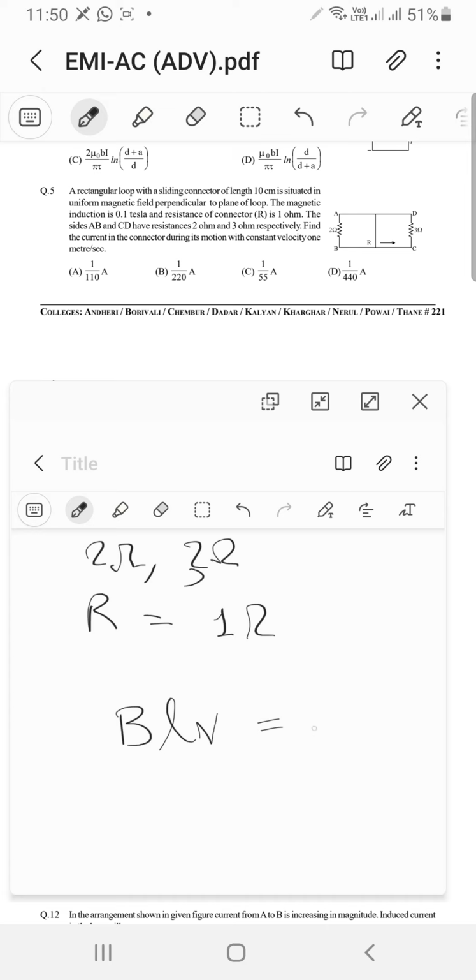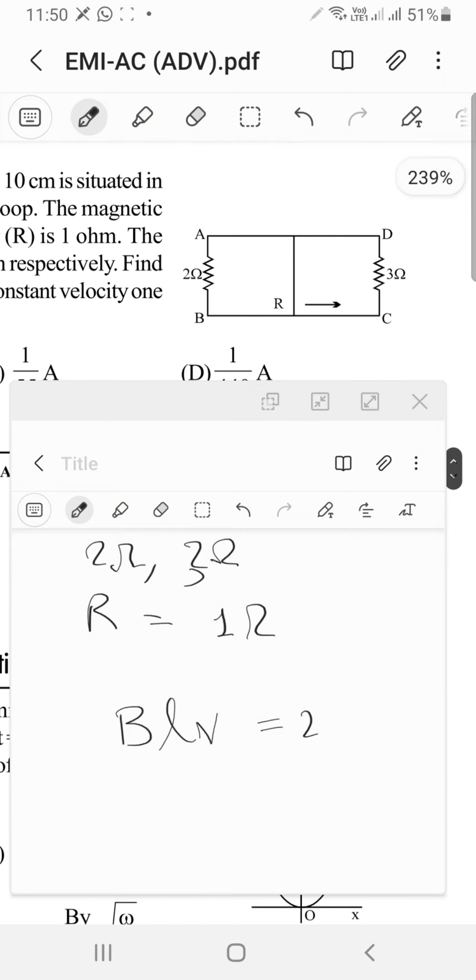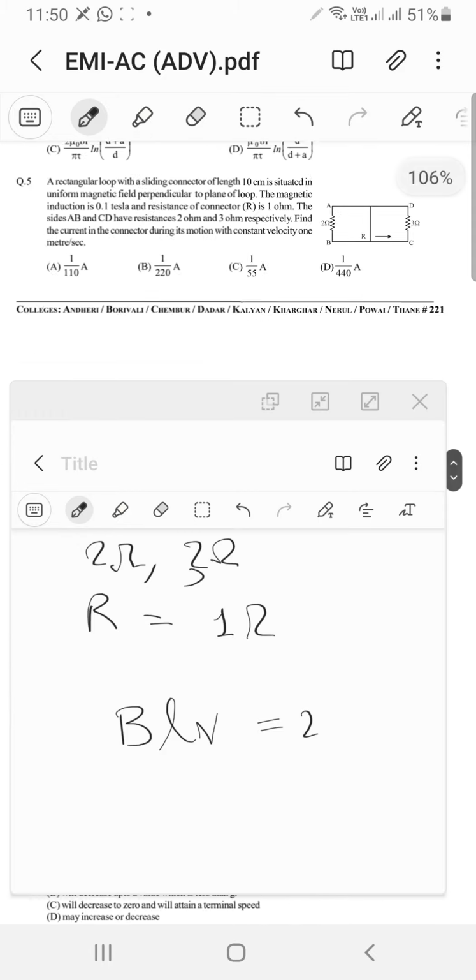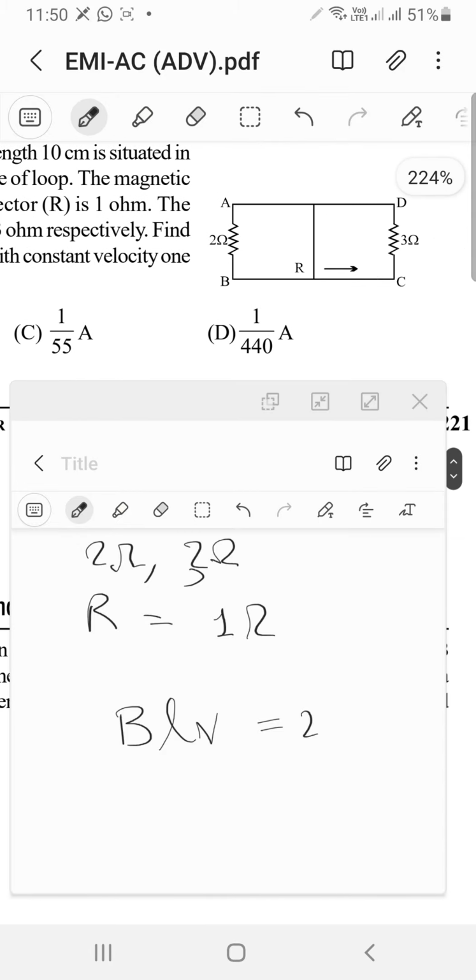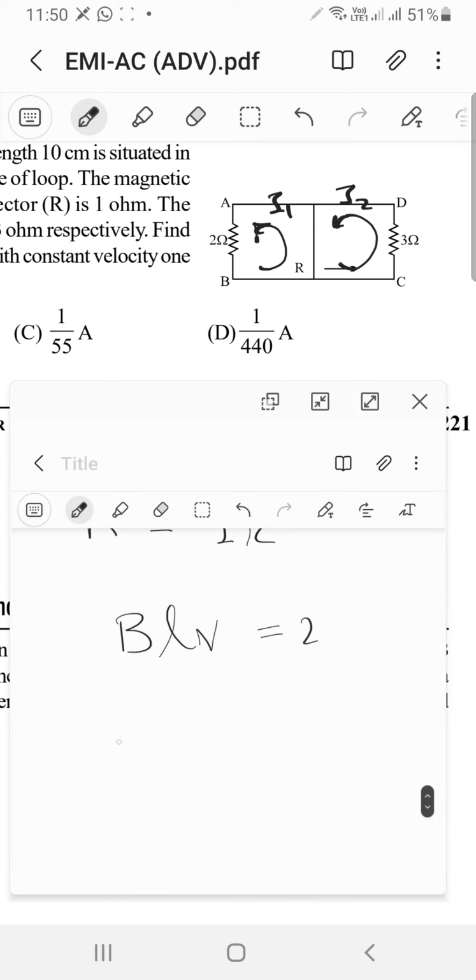So just say this is I1 and this is I2, so I'm going to assume the sign conventions over there. Yeah, so this is going in that direction. The magnetic flux in this is increasing, so it will try to decrease it, so the current will go in this direction. Right? So we will say, okay, fine, you got I1 in that direction, and let's just say that I2 is in that direction, right?